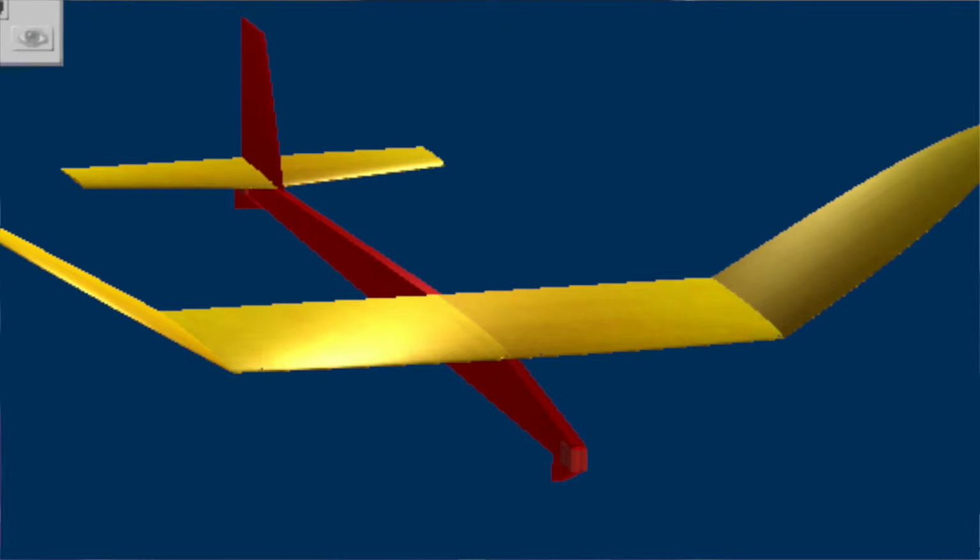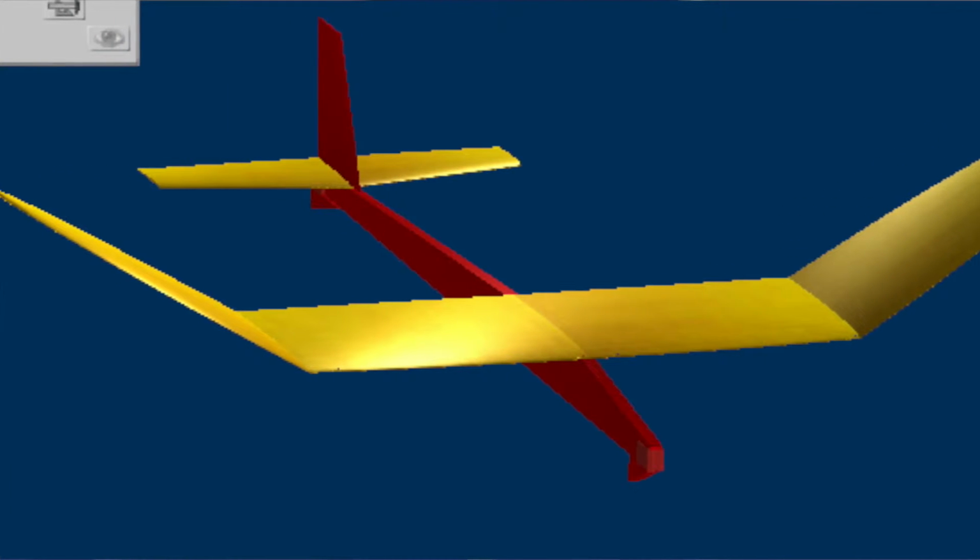All right, Joey, what have you done for this project so far? My main task for this project has been designing the planes in White Box Learning. This program is an online program that allows us to design the planes and then test them online. But when we went to test them in real life, we found some flaws with the program that didn't necessarily match up. When we looked at the shape of the wing, it said that the curved wings would work much better on the program than they really did in real life, and we found that the straight line planes work just as well, and if not better in some cases.